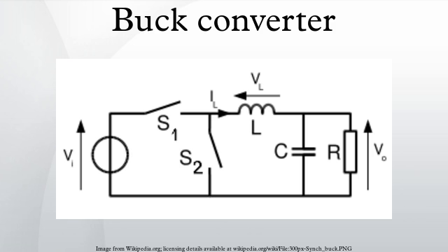Output voltage ripple is typically a design specification for the power supply and is selected based on several factors. Capacitor selection is normally determined based on cost, physical size and non-idealities of various capacitor types. Switching frequency selection is typically determined based on efficiency requirements, which tends to decrease at higher operating frequencies, as described below, and effects of non-ideality on the efficiency. Higher switching frequency can also reduce efficiency and possibly raise EMI concerns. Output voltage ripple is one of the disadvantages of a switching power supply, and can also be a measure of its quality.